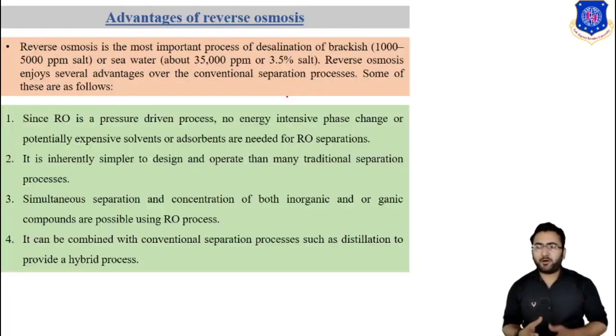Now let's discuss the various advantages of reverse osmosis. Reverse osmosis is the most important process for desalination of brackish water or seawater. It enjoys several advantages over conventional separation processes. Since RO is a pressure driven separation process, no energy intensive phase change or extensive solvent or absorbent is needed.